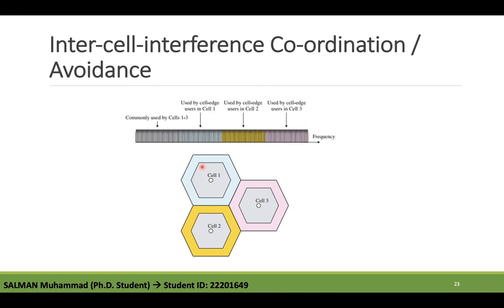The inter-cell interference coordination restricts the time frequency resources that are available at the resource manager or the transmit power that can be applied at certain time and frequency resources. The restriction on the allocation of resources or transmission power will provide the possibility for improvement of the received SINR and achieve the user throughput at the cell edge based on the corresponding time frequency resources in the neighboring cell.